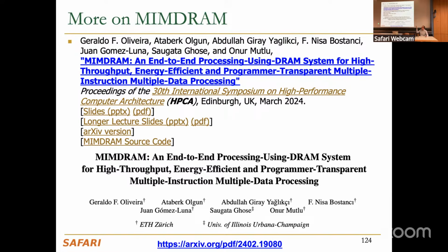And there are some things that are not easy to do using DRAM. And you can actually move the data and do the near memory processing in the logic layer and then move the data back, right, to another layer potentially. So clearly 3D stacking enables that, but that's near memory again. I don't know if it helps you to do better using memory. It's good to think about how you can take advantage of 3D stacking for all of those structures to actually do data movement, etc. It's a good topic to think about.